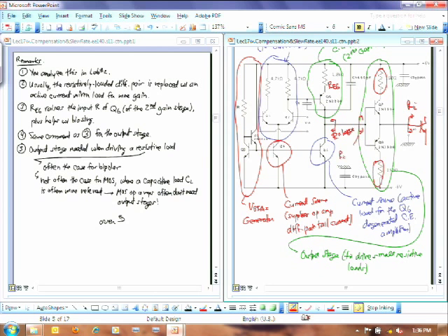But now look at the driver stage. Look what it is. It's this clever way of, it's not an inverter, right? It's kind of the opposite of an inverter, because I've got my emitters on the insides here, right? With the emitters on the insides, what this is doing is it's presenting a very small resistance looking that way, about a 1 over GM and a 1 over GM that way. And this transistor at the top will be used to pull voltages up. This transistor at the bottom is used to pull voltages down.